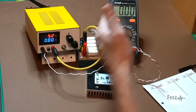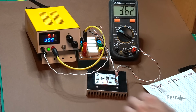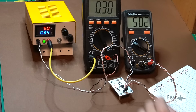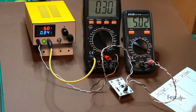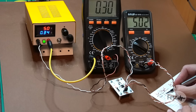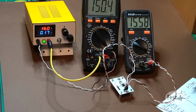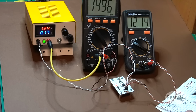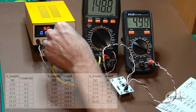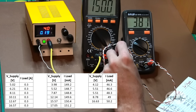So here I connected the constant voltage circuit through a resistor to the power supply, and while I'm varying the voltage on the supply, the voltage present on the active load is fixed. Next, I tried the constant current sink with variable levels of input voltage, and this setup was used without any extra heatsinks. So while this does work, as the board, especially the shunt resistor, gets heated up, the current did end up varying quite a bit, so the exact value was temperature dependent. This was probably the case with all of the other boards to some extent, but here it was far more obvious.